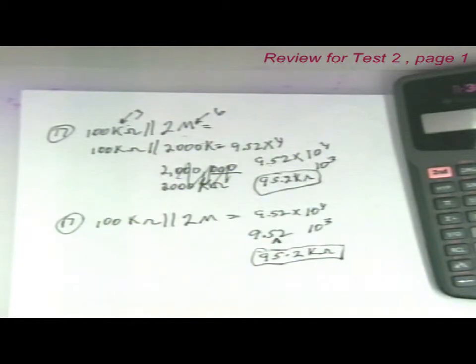The total power dissipated by a parallel circuit can be found by adding the individual powers. Well, yes, that's true, because PT, the total power in a parallel circuit, is equal to P1 plus P2 plus P3, etc. If one branch of a parallel circuit shorts, what does that mean? It shorts. That's where it's shorted out. Now, if you short out one branch of a parallel circuit, you're going to short out the entire circuit. So what's going to happen to current? Current is going to increase, isn't it?